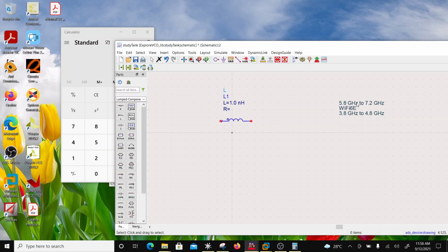And there are advantages of designing an oscillator at a frequency which is different from the output frequency, and that advantage is that the VCO is not going to be pulled in by a blocker. So I hope you understand why I have chosen a different frequency for the VCO than the output frequency. Now I want to design in this frequency range.